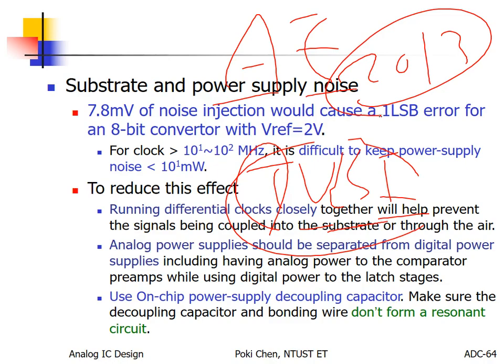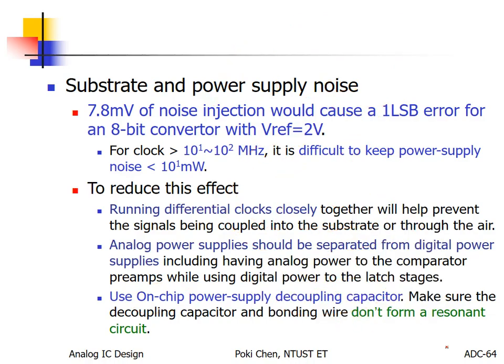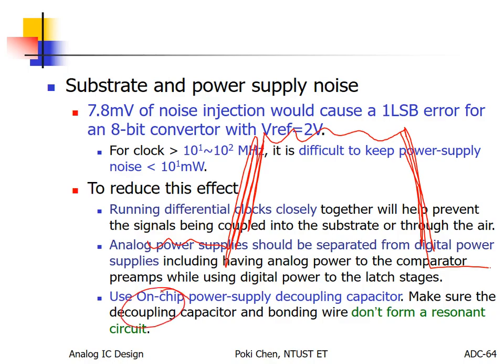The other thing to remind you of is the on-chip decoupling capacitor. It is really important because one of my students, one of the TAs, got the chip back and days ago measured the oscillator. Yeah, it works, but with some noise on the oscilloscope. He saw something like this. Wow, I was amazed. Do you have such on-chip decoupling capacitor? I thought the answer is no.